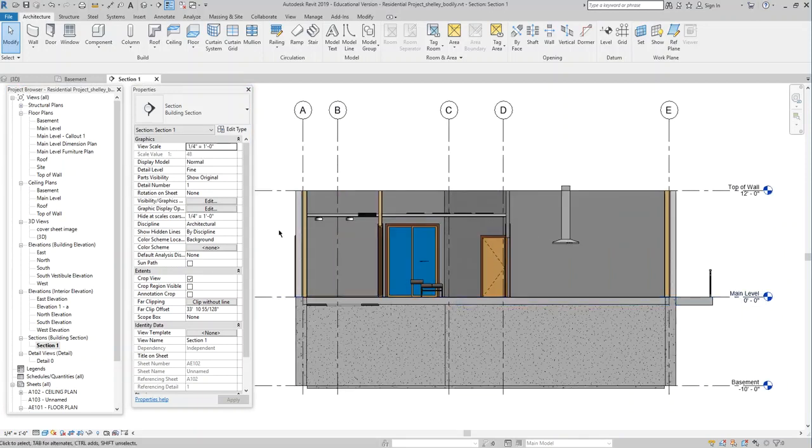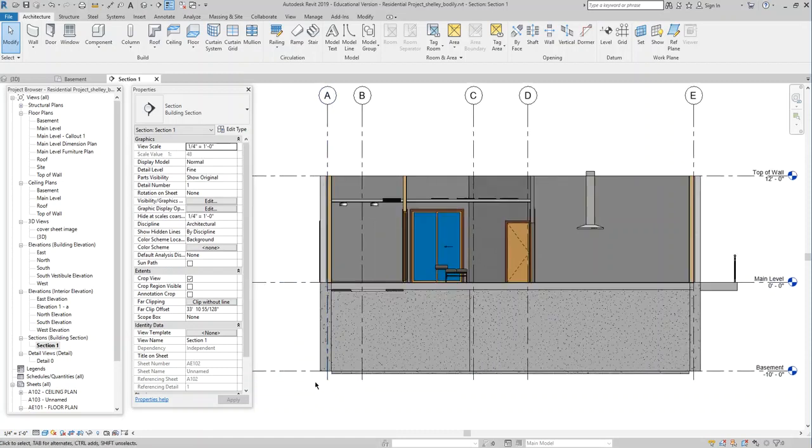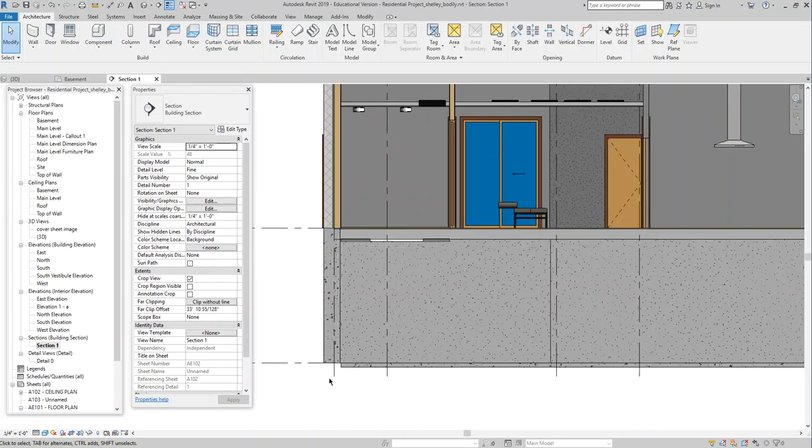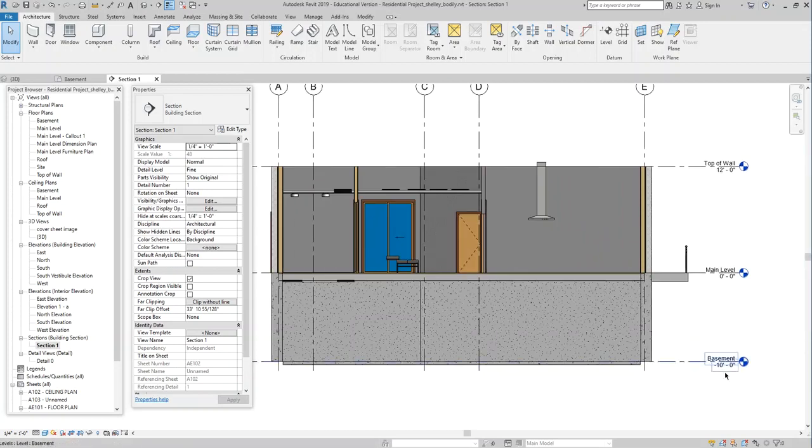All right. Any questions on creating the foundation walls? All right, let's create our footings then, right? Our footings are going to be the support for our foundation wall that spreads the load of that giant point load coming down onto the earth, right? So we need to create our little footings. I'm going to make them larger than they need to be so that we can see how big they need to be. But right now, I don't really have everything I need just yet to really define them.